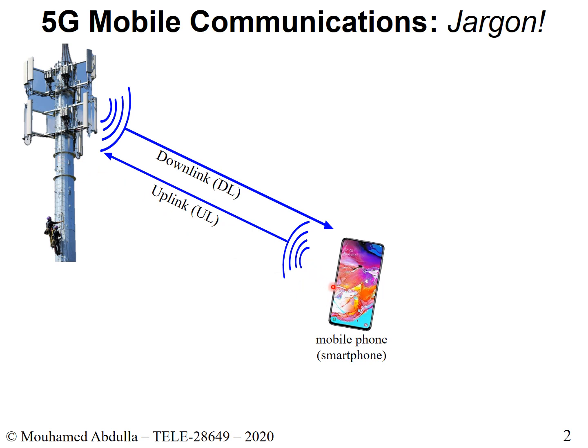And you are able to do this because you don't have a simplex communication. This is a duplex communication. And it's not a half duplex communication. It is a full duplex communication. A half duplex communication is a communication where you are only able to transmit at a certain time, and then when your time is up, the other person transmits, right? So you split the time that you do your communication. This is a full duplex communication.